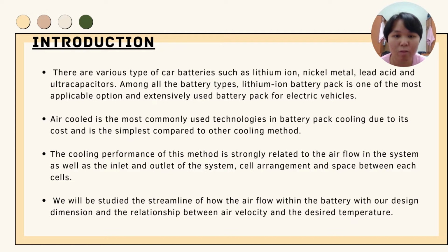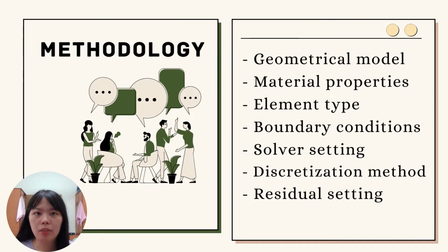The cooling performance of this method is strongly related to the airflow in the system, as well as the inlet and outlet of the system, cell arrangement, and space between each cell. We will be studying the streamline of how the airflow moves within the battery with our design dimensions, and the relationship between air velocity and the desired temperature. So the next part is the methodology.